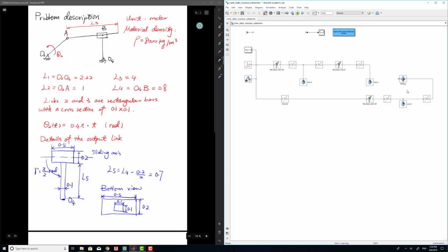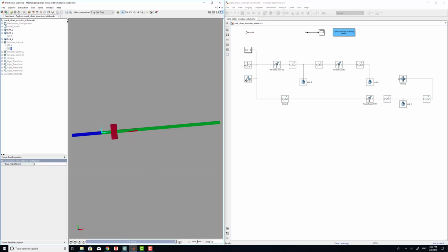And then on the other side, let's check the coordinate. This sliding joint needs to connect to your link number 3. So we need to make sure that the length direction of your link number 3 is actually the z-axis. Let's find your link number 3 coordinate, and you can see that the direction of the length, or the sliding motion we want, is not along z, it's actually along x. That's not good. So hence we have to do some rigid transform.